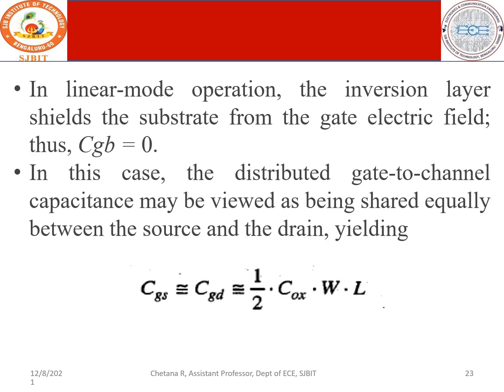So now we will have a look into the capacitance involved, or what is the status of the capacitances in the linear mode. In the linear mode we see that the junction is almost ready to be created and the process involved is inversion. Therefore the inversion layer is created. Almost the channel is created, by the influence of the gate voltage and the drain voltage, and limited amount of current flows from source to drain. So whatever is the amount of voltage applied, proportionately that much current flows in this particular channel in the linear mode.